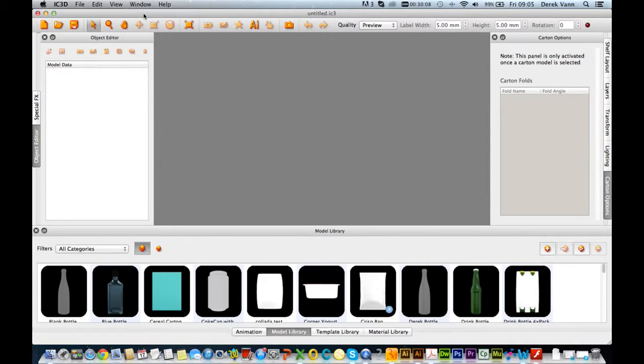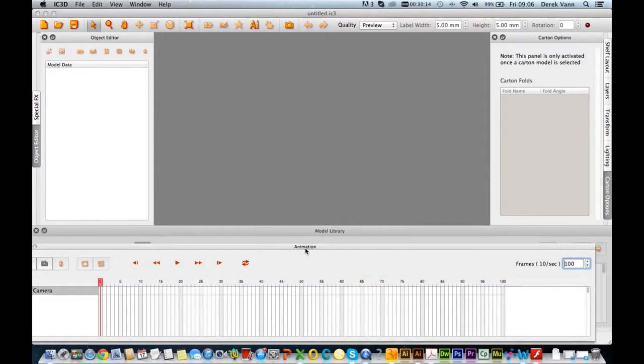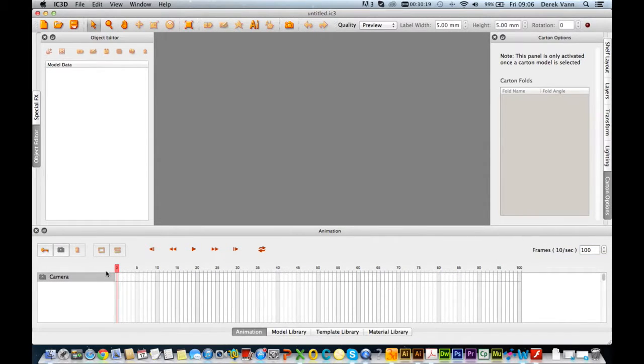The animation window is selected from the Window tab and can be docked alongside the model templates and materials windows for ease of use. The timeline needle can be moved across the grid to aid production of the animation, and the Enable Animation button records the sequence.